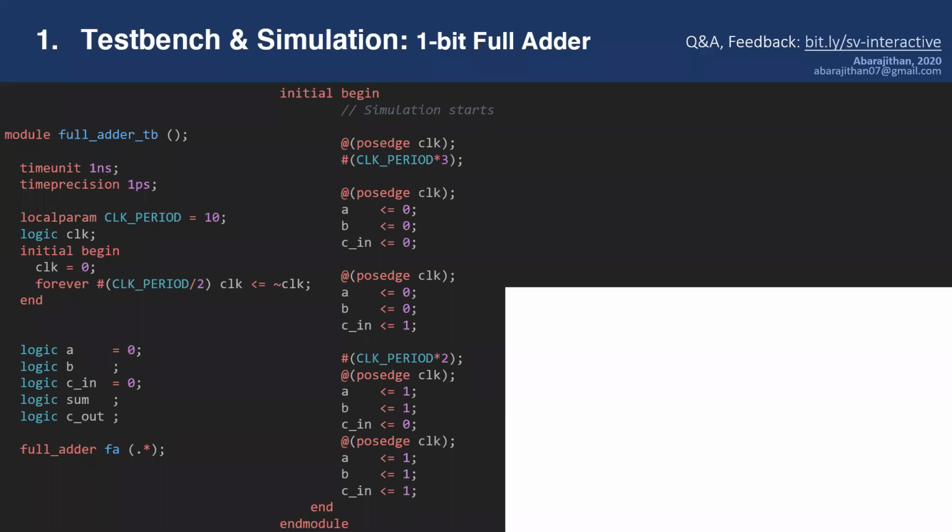So how is it implemented on chip? In the RTL, we are telling the synthesis tool how to create the circuit. We tell what the inputs are, what the outputs are, and how they are combined: the AND gates, OR gates, and everything. Then the synthesis tool, which we will look at later, will convert that into actual logic gates, or in an FPGA into LUTs, lookup tables, and flip flops and everything. We'll look at that.